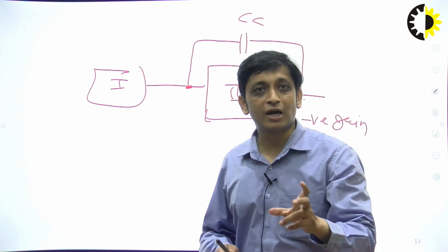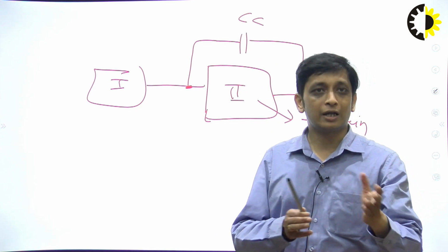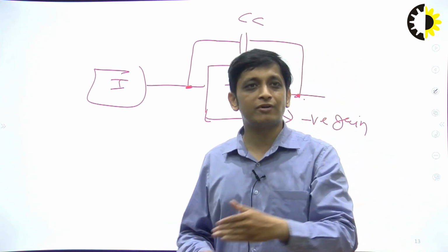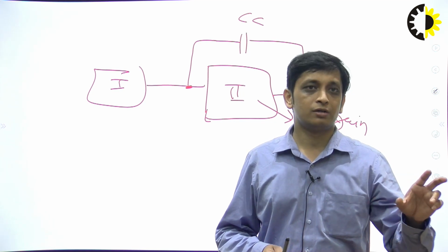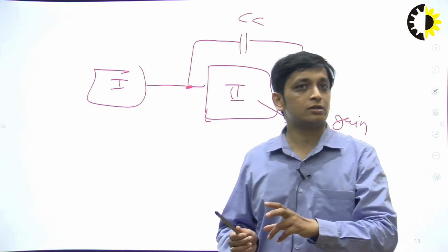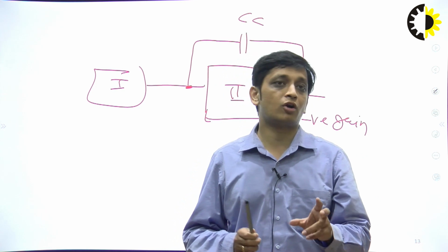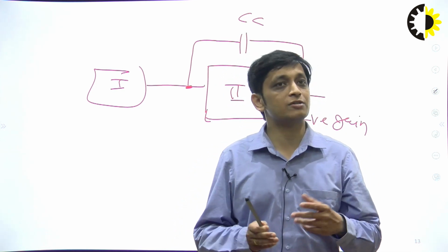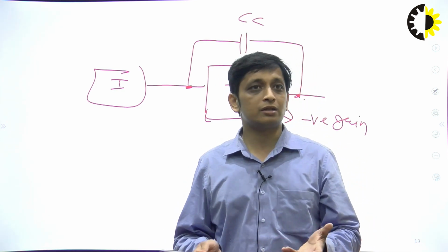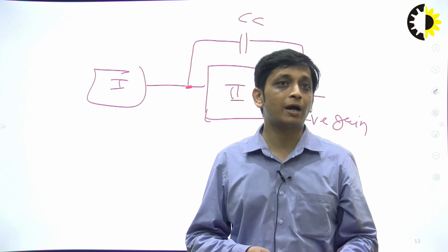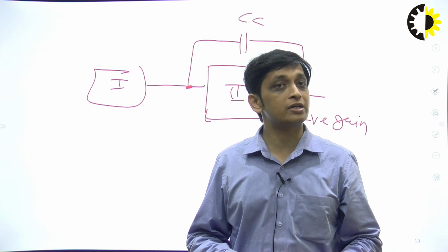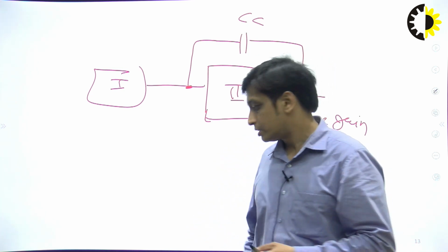So which amplifier gives negative gain? That amplifier is the common source amplifier when we go for MOSFET amplifiers, right? It is very important. The Miller loop gain should be negative in order to stabilize the circuit. If it is positive, then the circuit stability is compromised. Then it may form positive feedback, and the amplifier becomes unstable. So it's an important thing, right?